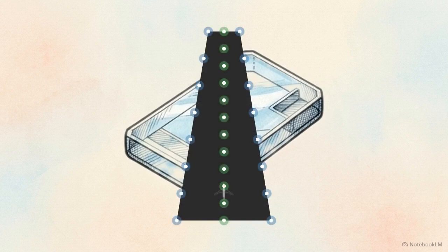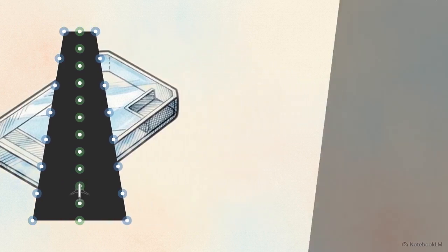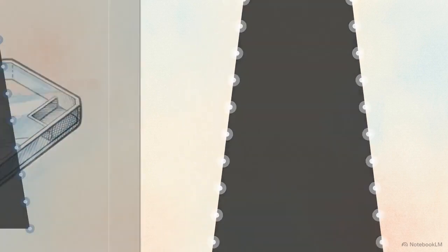Once activated, this isometric layout ignites with a strict color code. Taxiway boundaries are defined by omnidirectional blue edge lights, while the exact center path is marked by a line of green lights. Transitioning to the active runway, the blue edge lights are replaced by high-intensity white lights. The runway end lights utilize a split-color lens, displaying green to incoming aircraft to mark the safe threshold, while showing red to planes rolling toward the far end.